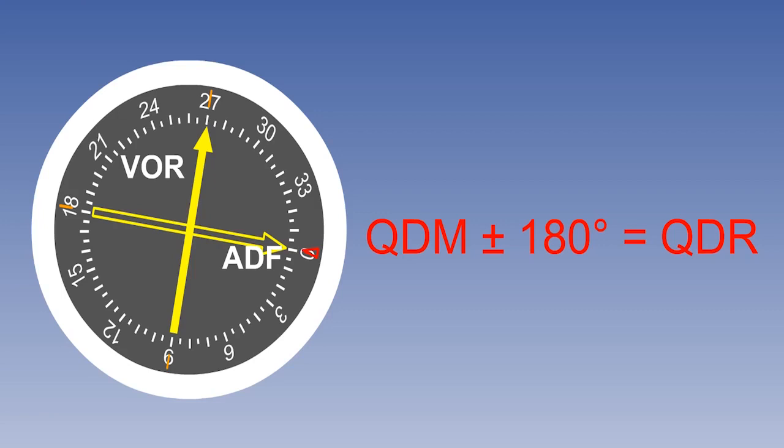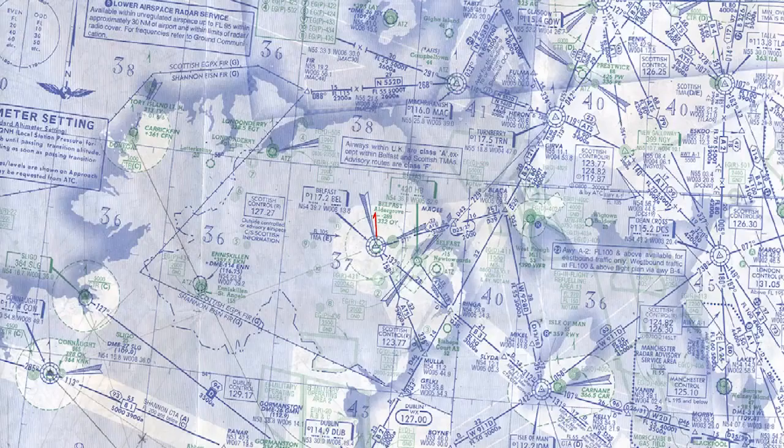There are 4 possible ways to plot it. You could align the protractor with a magnetic north arrow, if there is one. The problem is that these tend to be very short, usually just over 1 centimetre, and it is difficult to align the protractor accurately. Remember, we said that accuracy was important.